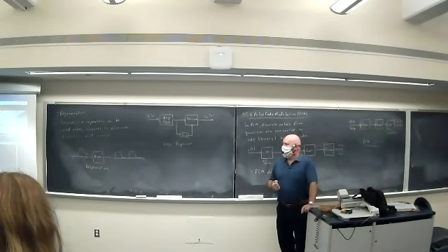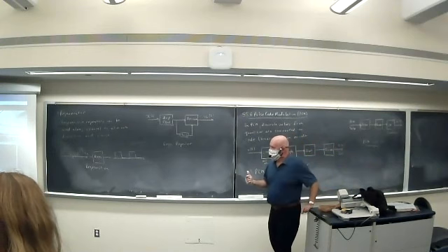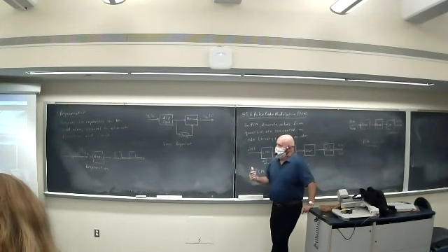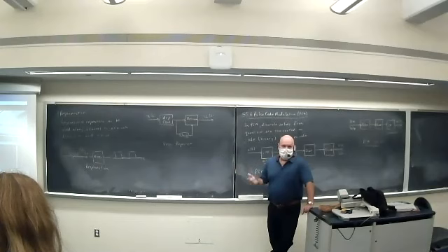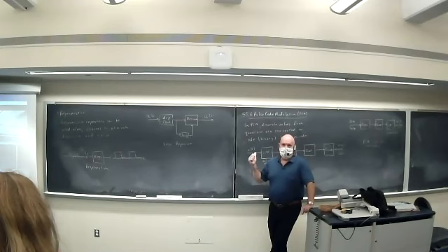The other thing that digital systems allow us to do is transmit additional error correction codes or bytes that we can use to indicate whether or not an error occurred in the transmission. Something like a parity bit would be a simple thing on every binary word to make sure the parity is correct.